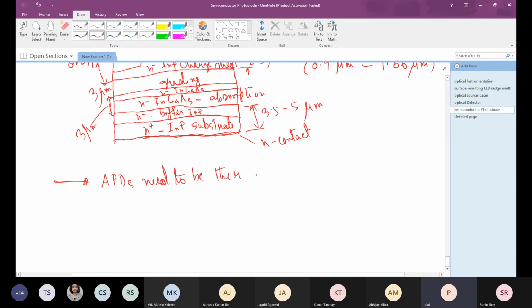If not by liquid nitrogen like the photomultiplier tubes, at least thermoelectric cooling is necessary to get a stable gain, because with respect to temperature the gain may change drastically.